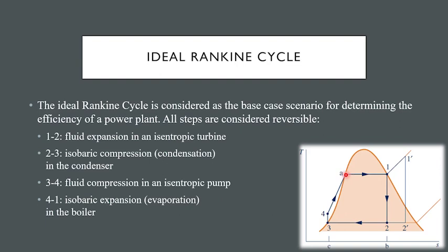And if we consider the net amount of work generated as the area enclosed by the cycle, the Carnot cycle has a lesser area than the simple Rankine cycle. Okay? Because this five-sided polygon for the ideal Rankine cycle has a bigger area than its equivalent rectangle representing the Carnot cycle.